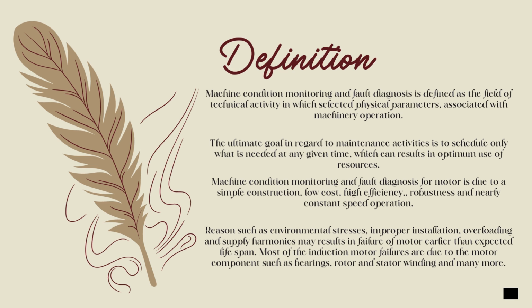Next, machine condition monitoring and fault diagnosis for motors is needed due to their simple construction, low cost, high efficiency, robustness, and nearly constant speed operation. Lastly, reasons such as environmental stress, improper installation, overloading, and supply harmonics may result in failure of a motor earlier than its expected lifespan. Most of the induction motor failures are due to motor components such as bearing, rotor, stator, winding, and many more.